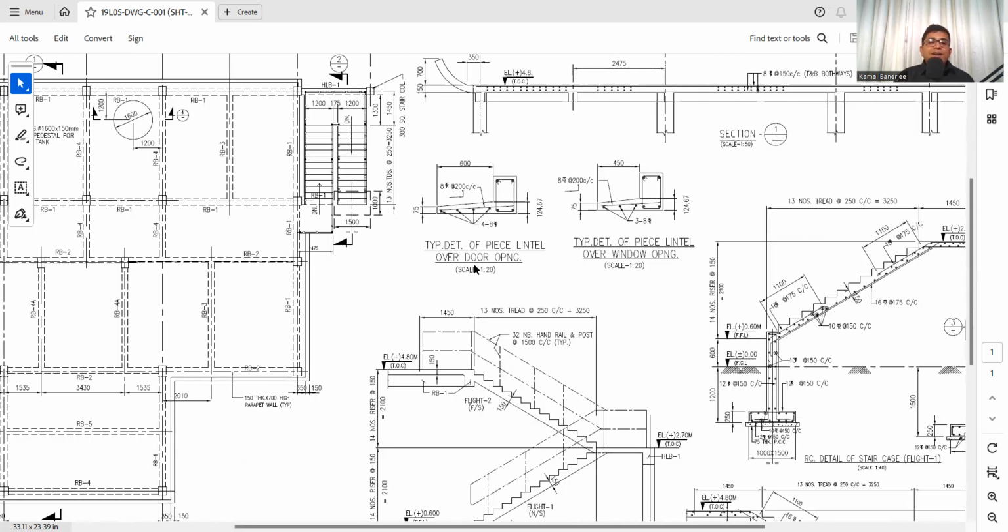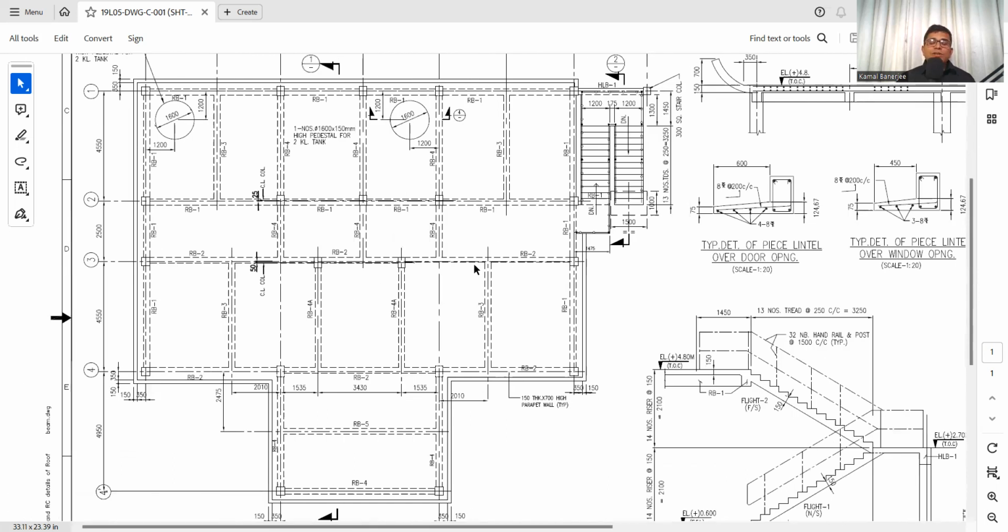So whenever we are dealing with slab reinforcement or preparing a bar bending schedule, we need to check the beam slab arrangement, then slab spanning, slab geometry, slab cover, slab reinforcement, and whether there is any MEP cutout, any special reinforcement, any pedestal, and then the clear cover, and then the parapet we need to check, and accordingly we need to prepare the bar bending schedule of the slab. So these are all the structural drawing reading of the slab.